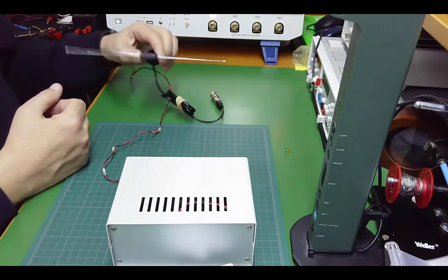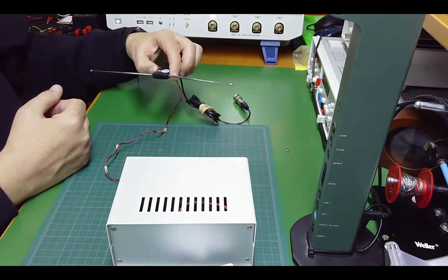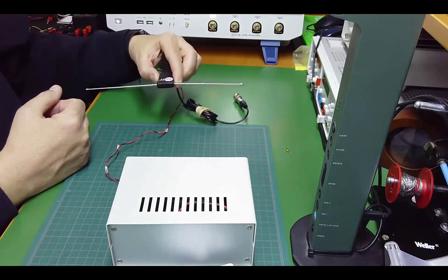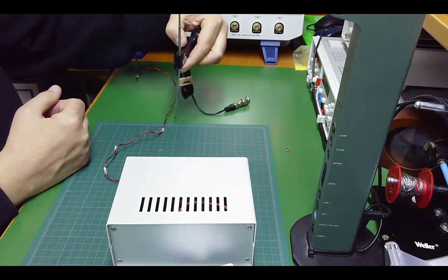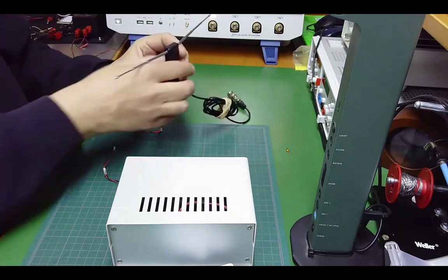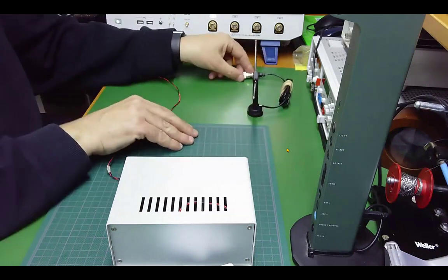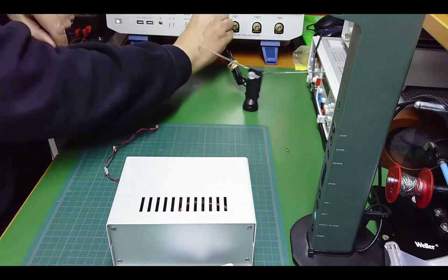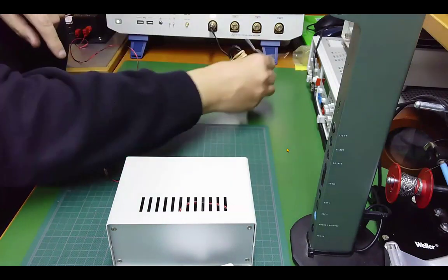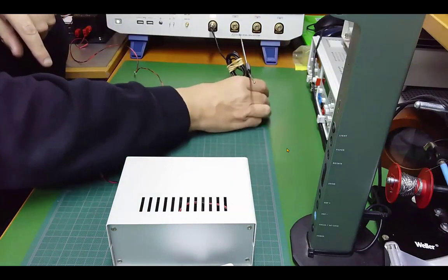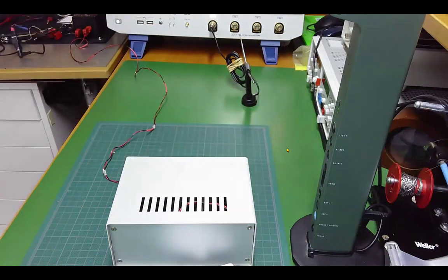If I put the antenna in this position, I am measuring horizontal electric fields. If I put the antenna in this position, I am measuring electric field that is vertical. In my demo, I will not be very scientific. I will put the antenna in this position, and we will connect the output of the antenna to channel number 1, okay? So this is what we have, basically. Now we are able to switch on the device.